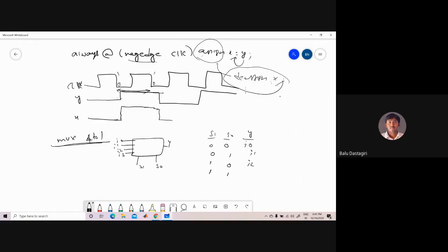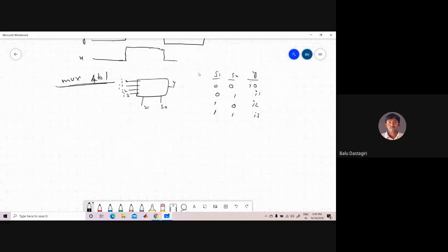If the selection lines are 1 1, it means I3 is connected to the output Y. So this is what we have to write the program for, that is the behavioral program. Now, how you can write it by using the assign statement is...